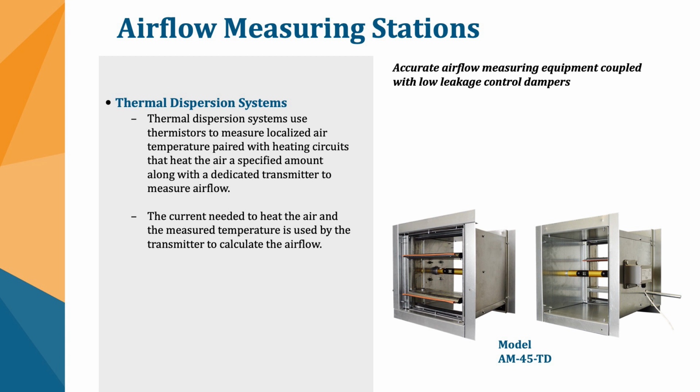And in fact, most of these units are set up to where the airflow goes to the probes before it hits the damper. You really want to set it up that way, so that you're not necessarily throttling your intake before the probes. You're actually throttling it after the probes. That works to create that laminar flow I was talking about. The non-laminar flow tends to force an increase of the length of your ductwork before the probes when you're using any type of damper, if you put it upstream of the measuring device.